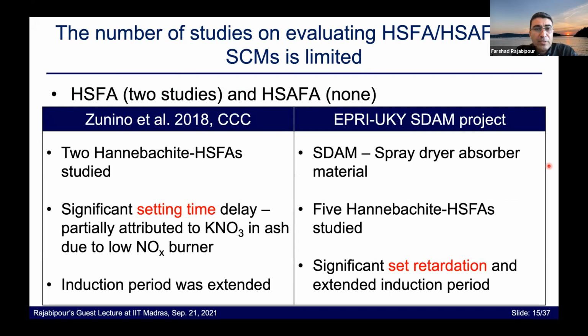All right, very briefly, the literature on looking at high sulfur fly ashes is fairly limited. We've found two main studies that focus on these high sulfur Hannebachite or calcium sulfite containing fly ashes, and very briefly, they both suggest that one of the main issues with the use of these fly ashes is a significant setting time delay. They don't explain the reasons or how this can be mitigated, but they report that the presence of Hannebachite can cause setting delay of Portland cement mixtures.